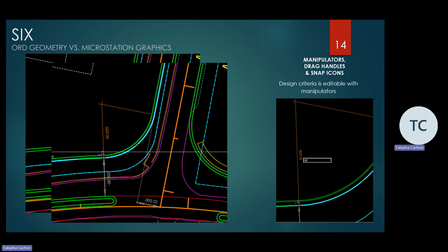And that's where you really have to be diligent in the way you lay these things out, because I learned the hard way. I started out laying it out with ORD geometry, and I somehow ended up drawing regular MicroStation lines. When I changed my radius, the stuff downstation didn't change. So pay attention to how you lay this out using ORD geometry with feature definitions. And you can notice with a simple click, I can change the radius of that arc. This is just one small example.